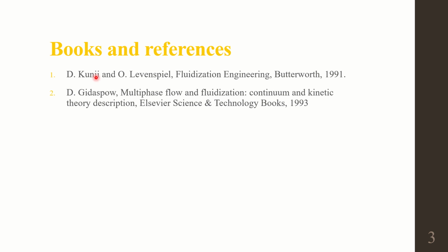As we discussed before, fluidized beds can be modeled in two ways, wherein we model the fluid as a continuum, but for solids we have two descriptions, either as a continuum or as a Lagrangian, that is, as discrete particles. In the continuum theory description, we average the solid properties by imposing a theory similar to the kinetic theory of gases.